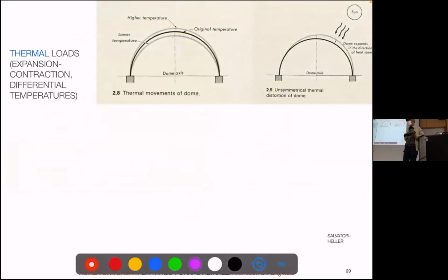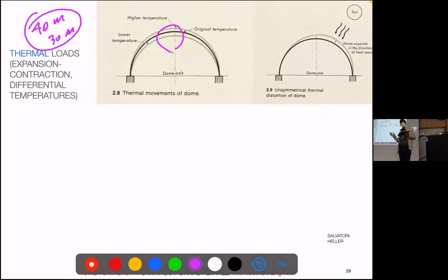More important, especially in big spans, what we commented on: thermal loads will make elements deform quite a lot. Usually we have a limit of 40 meters, right? Or 30 meters, not to consider thermal load. So if buildings are smaller than that, probably it is okay. But in very slim and light structures, as in roofs, maybe we have to consider them, right? It's additional stress. With cold, they will contract. With heat, they will expand. And we have bolted, welded joints, which may suffer from those expansions.